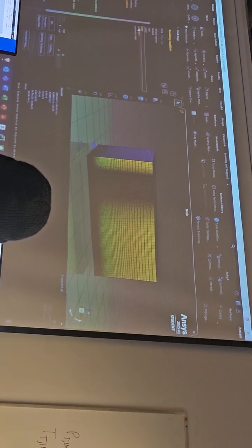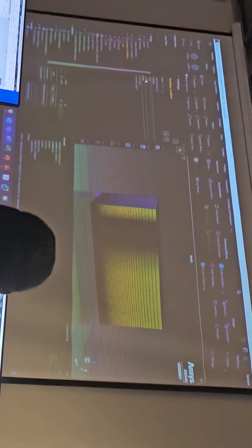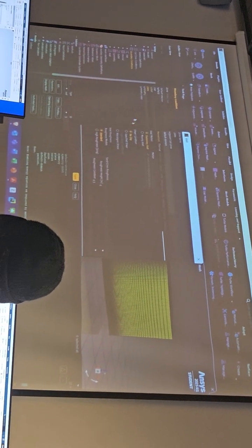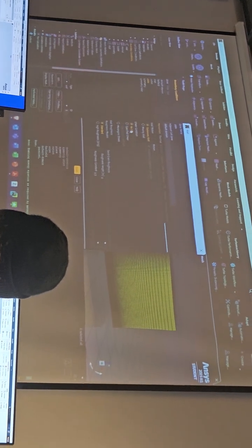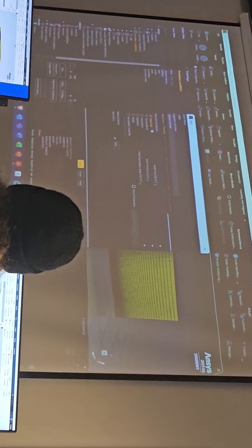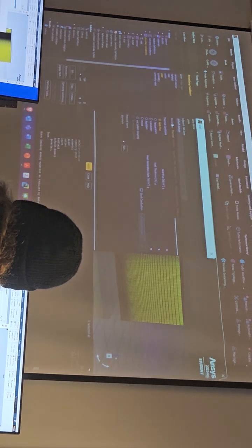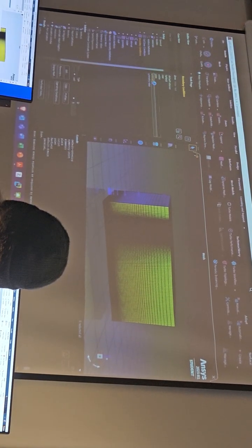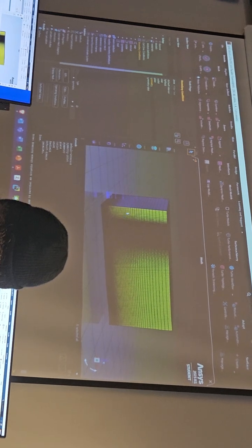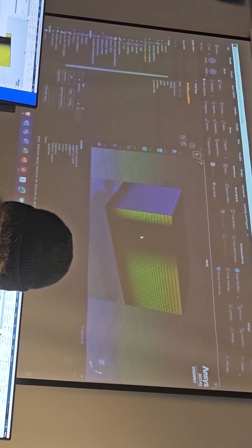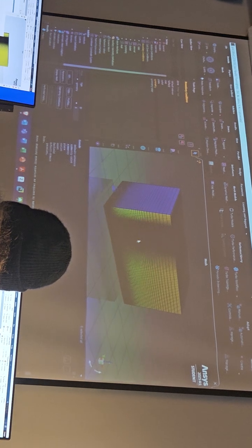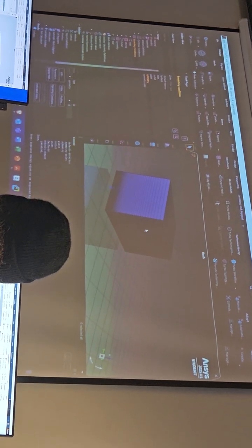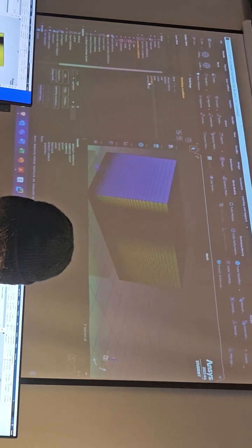Alright, then the plate, this is an adiabatic no-slip wall. By default, Fluent sets wall as no-slip, and also in thermal, the net heat flux is 0, so that means adiabatic, so we don't need to change the one for the plate. Then we have symmetry. Symmetry are these two surfaces on the right and the left sides of the domain, since this is a quasi 2D case, so 3D, and we can leave them like symmetries.